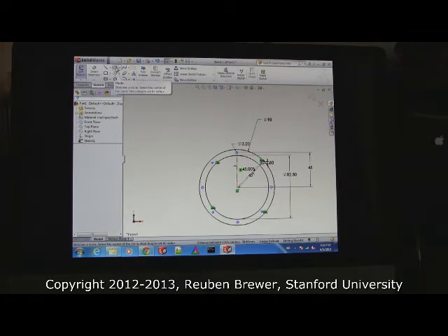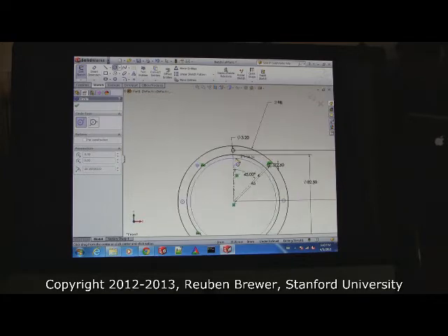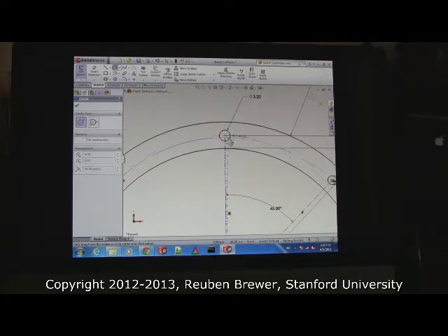So go ahead and take a circle. Put it in the center. Now zoom in as you drag up, and don't click anything. Watch my screen for a second. So I'm going to get near this other circle and watch. It's going to try to suggest some stuff. It's suggesting I be tangent there. It's suggesting I be tangent there. It's suggesting that I go in the center. It's suggesting that I go on top, well, on top of that circle. See how it turns red? So we're going to use one of the suggestions, which is we're going to put the circle running through the center of the other, and hit click.